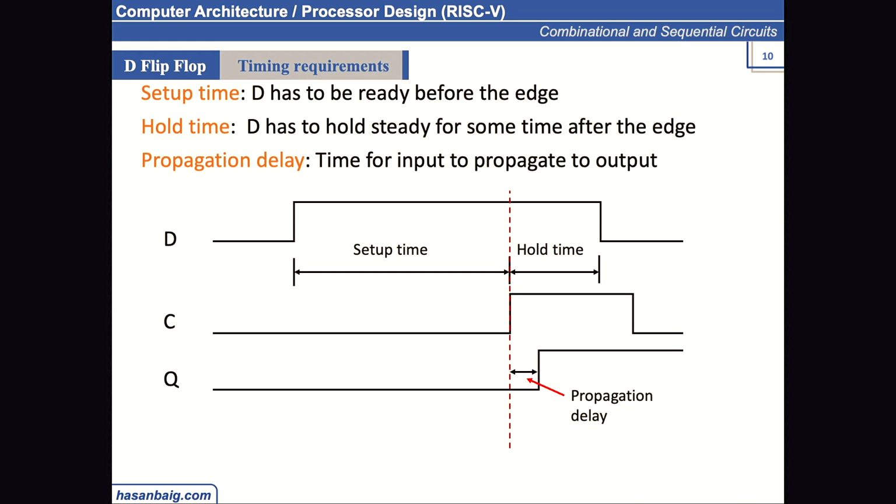So he read the data, right? And he went at the output. That is called the processing time. And the delay after reading the data and producing at the output is called the propagation delay. Okay? That is, the input data is propagated at the output.